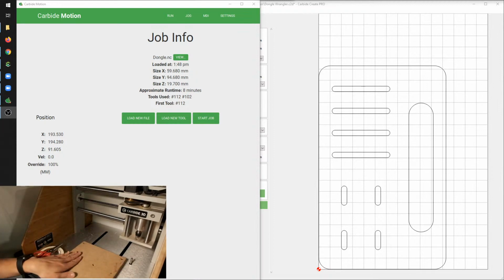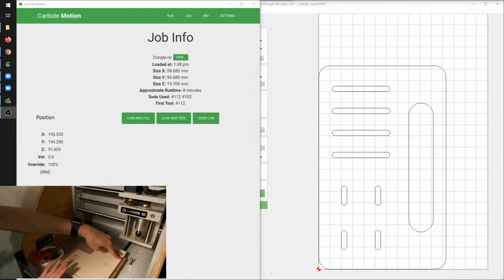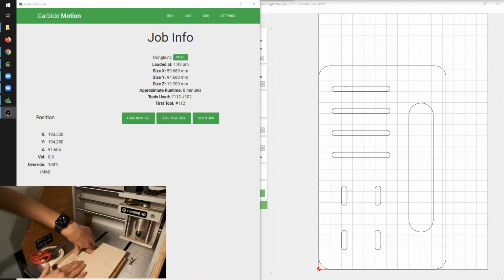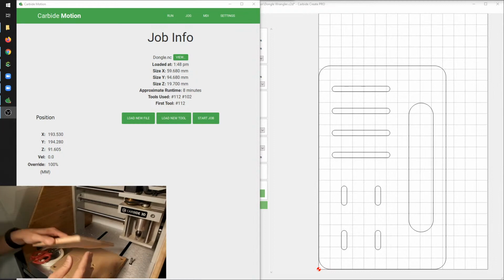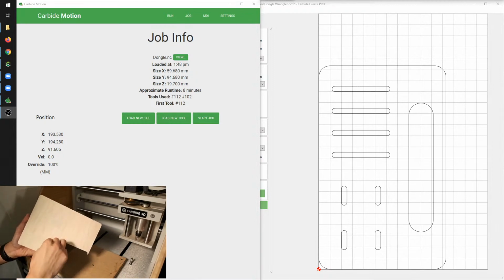I gotta figure out where tape's still clean. I'm just trying to figure out, is it because the stock is saddle shaped, or where that movement's coming from? I think it's the stock not being perfectly flat, and so when I press down on here, it levers this side up. So I might just leave all my tape, just a big chunk of it, in this quadrant. Could also be that the surface is dusty, but the tape is pulling up clean, so I don't think that's the case.